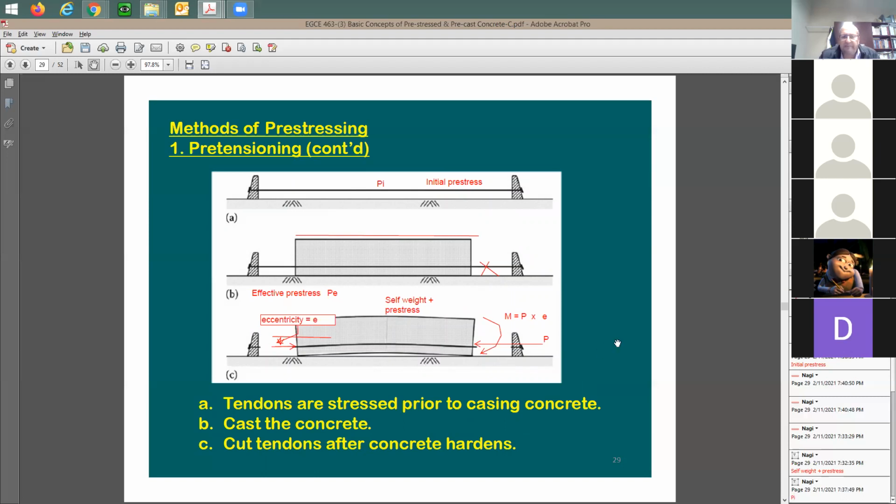This is a general statement. In pre-tension and post-tension, they like to reduce the rebars, right? All they want to do is apply the pre-stress and let go. They'd like to reduce the amount of work by people. So they are not interested in putting lots of rebars, unless when it comes to design you really need to put some non-tension steel, like the regular rebar. All right?